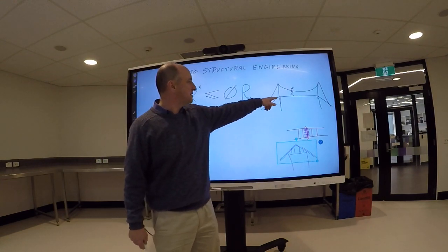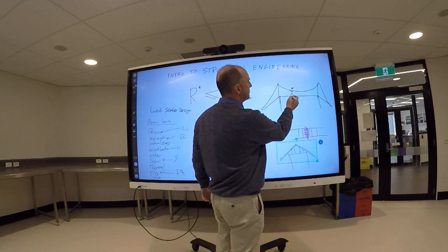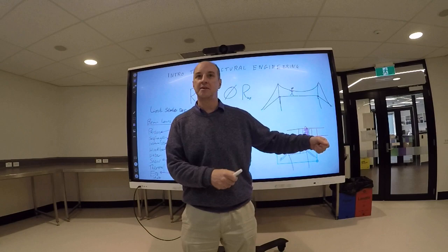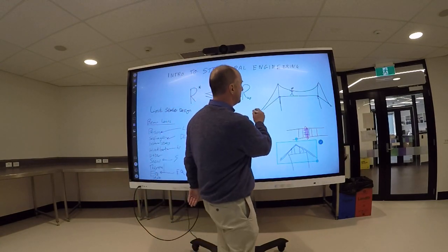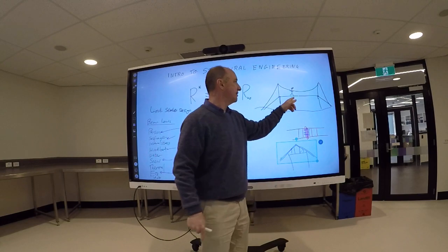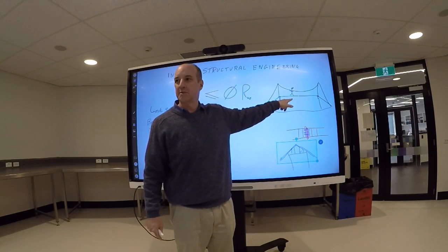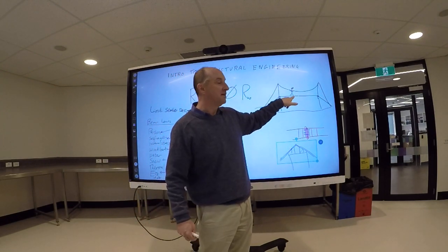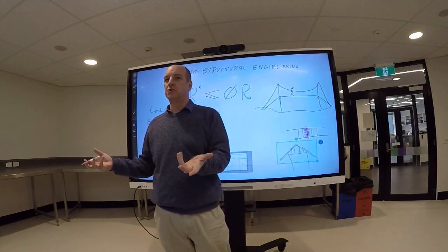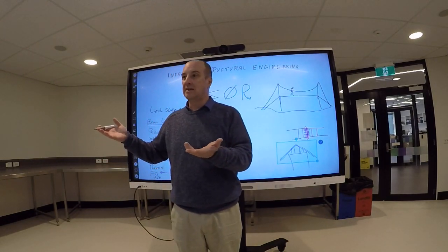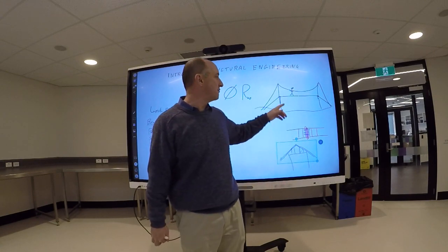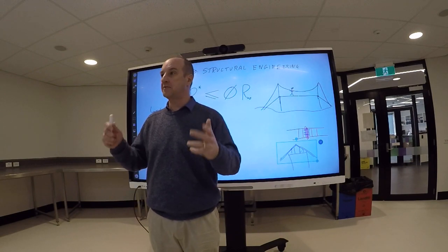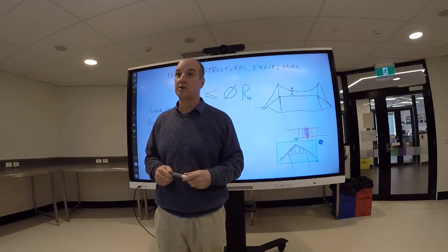Okay? This is a suspension bridge with this beam right here. And you know when you've been on a suspension bridge, it sways and shakes. Okay? If the world here is swaying and shaking, how much do you think that plank is going to be concerned about that? Not at all, right? Earthquake, we can ignore earthquake for a suspension bridge. What earthquakes do is they impose a deflection on something. So if you have a really flexible structure, it just moves with the earthquake, it's not really a problem. When you have stiff structures, that's when earthquakes are really a problem. Okay?